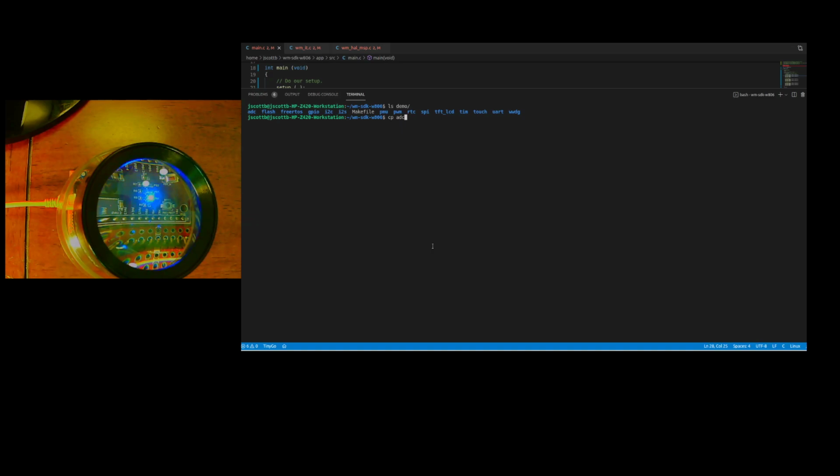I'm not going to do it, but copy the ADC demo to our app source directory, and it would replace those, and you would be able to compile those just like we did the Blink application or the Blink sketch. So you should be able to do that, and you're free to do that.